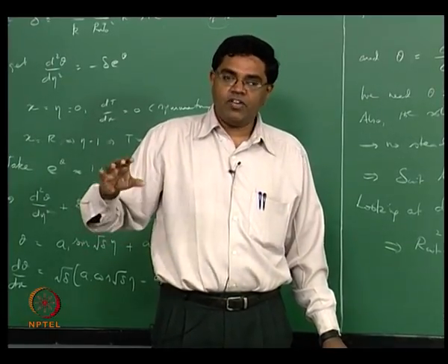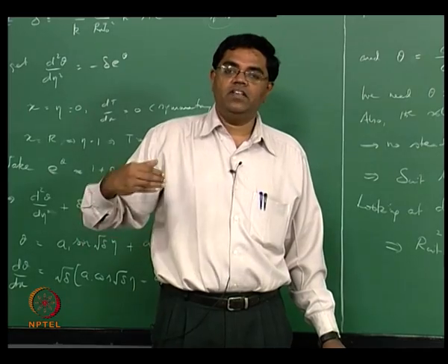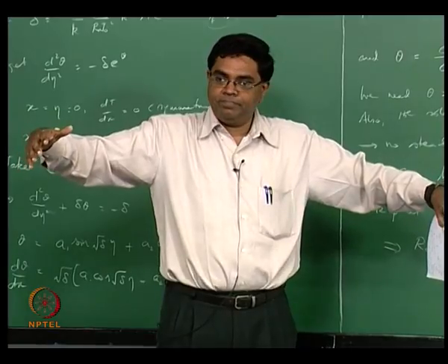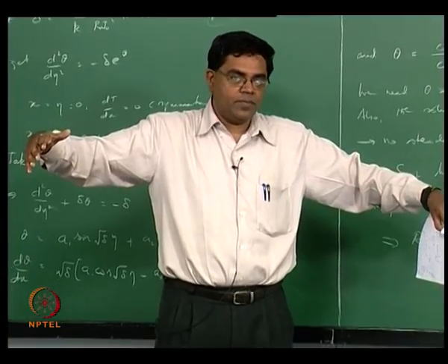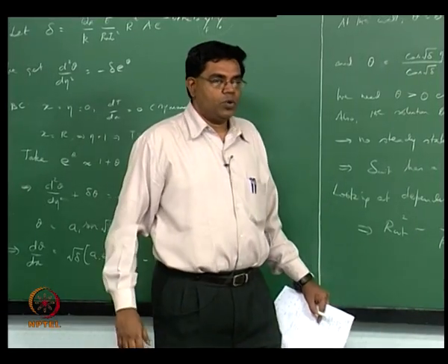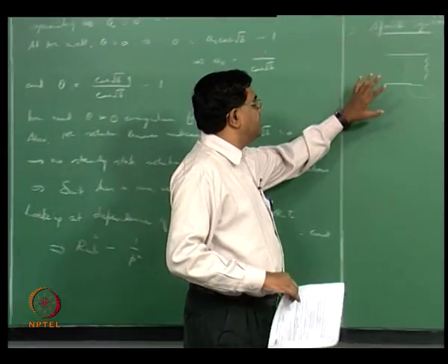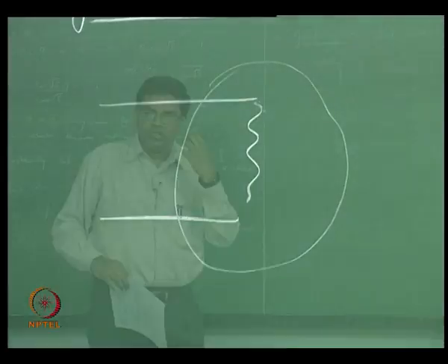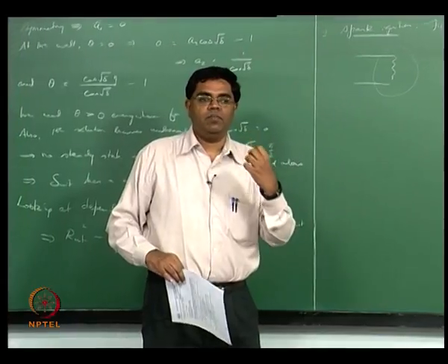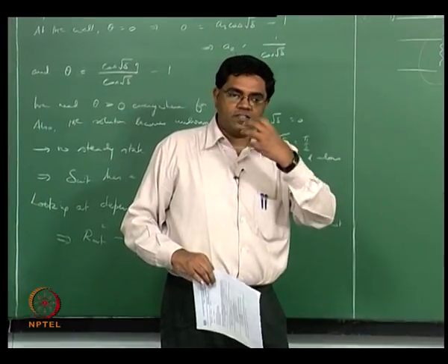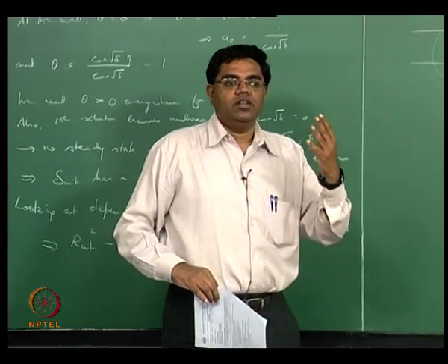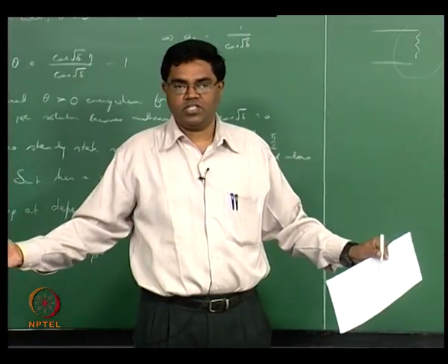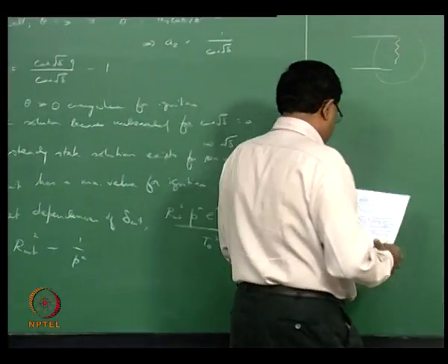Okay, but the reaction rates are so low that the heat release rate is so low that it's just getting conducted away to the surroundings from where it is happening, right? So therefore, what we are basically looking for is what's the energy that is being supplied by the spark that will actually ignite a critical size of this flame ball whose surface is so large now that the chemical energy release that's happening in this is sufficient to overcome the heat loss to the surroundings, right. So that's what we are essentially looking for.